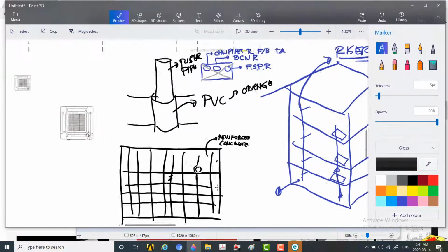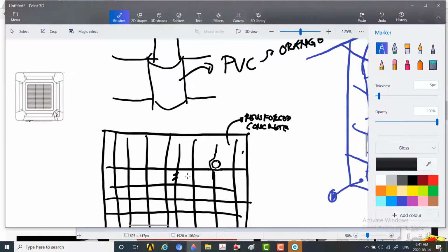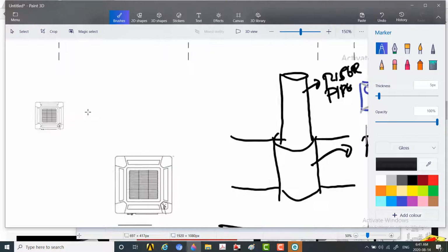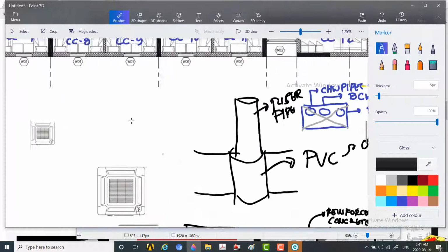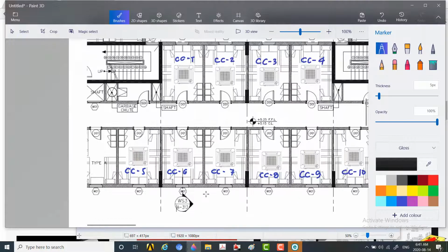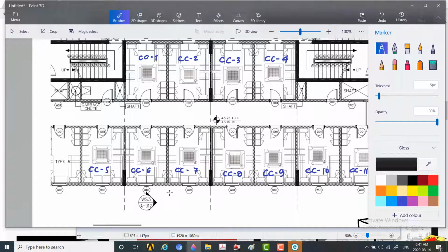So mostly pag ganun nangyayari, bubutasin mo reinforced concrete without the advice of a structural engineer or civil engineer, so eventually talaga mag-aaway kayo sa site. So magagalit yon. So take note, you have to inform them na you're going to pour. Okay? So as much as possible, huwag niyong puputulin yung rebars. So doon na kasi nakadesign yung strength nun.